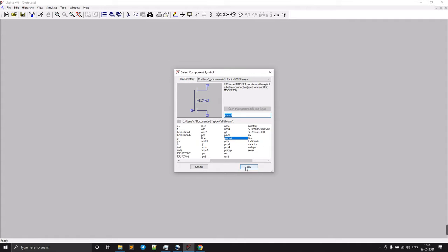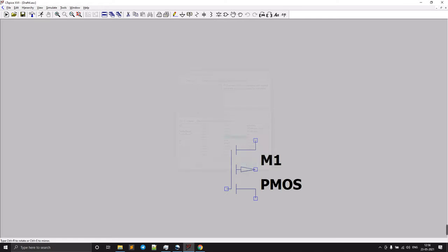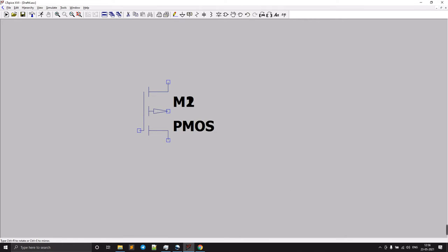We are using the monolithic MOSFETs. So yeah, this is one PMOS. Okay, we need two sources, that is VGS and VDS. So okay, I'm just giving the voltage. This is our input and this is our VDS. Okay, so this is the VGS. In the PMOS, remember there will be the P channel. So here we need to provide the negative voltage for the input.